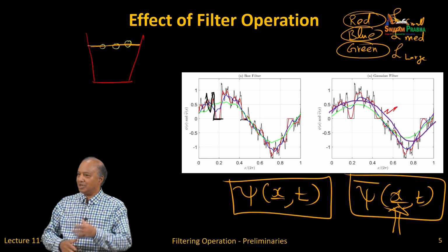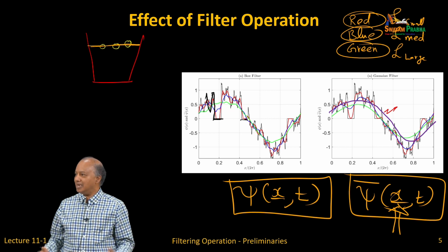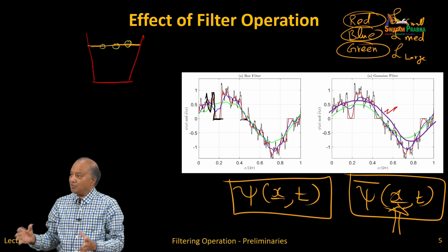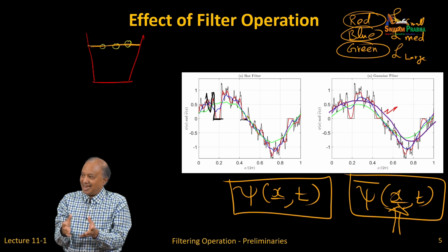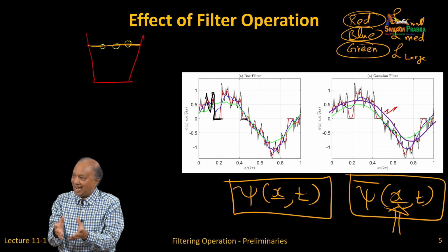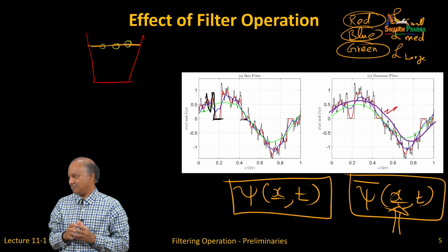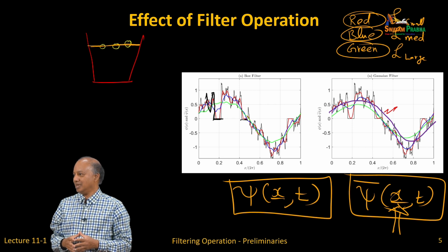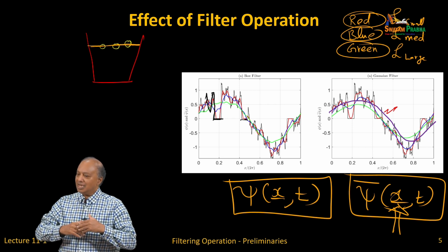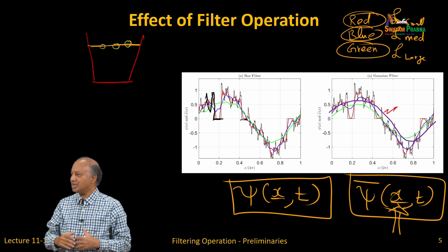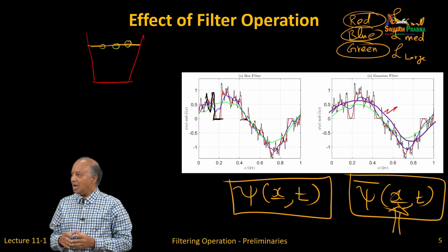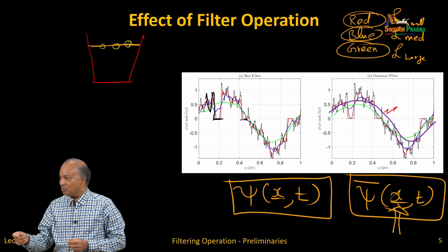So, in other words, if you have a fluidized bed and you do an ensemble average, you may have some big eddies, etc. Now, the RANS model is trying to compute that smooth flow, which has no turbulence, it is a smooth flow. That only depends on large scale variations or ensemble average variation. So, you have a much easier job of actually numerically simulating.